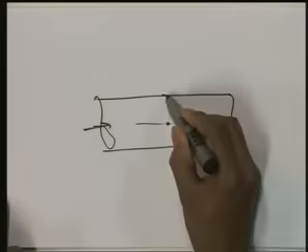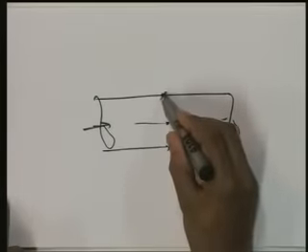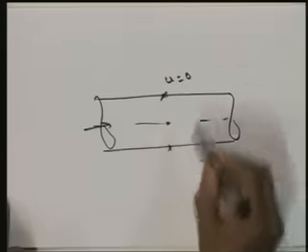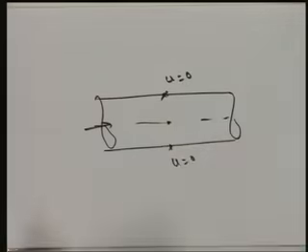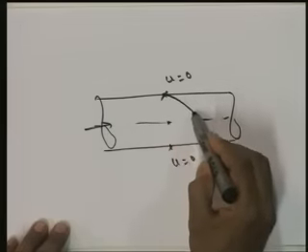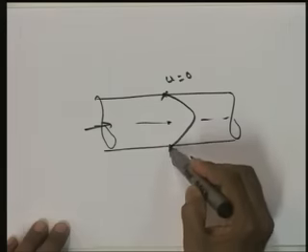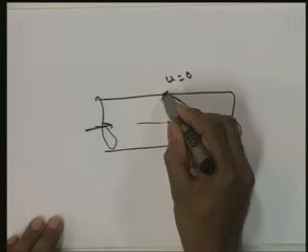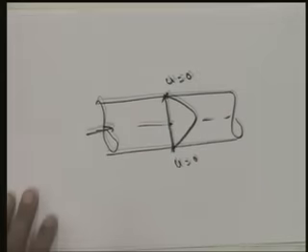So, due to the no slip condition on the pipe boundaries, the velocity will be 0 on the pipe wall, and then you can see that the pipe velocity will be maximum at the center, and then again on the other side it will be 0. So, with respect to this we can now plot the velocity variation for the laminar flow in pipes.